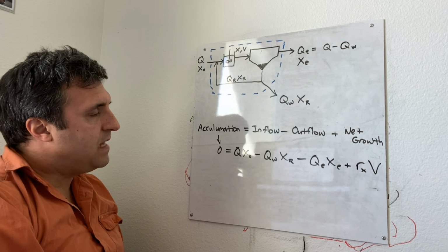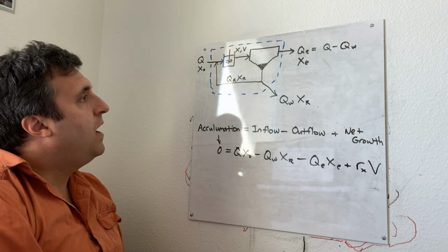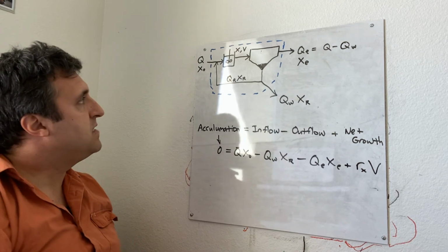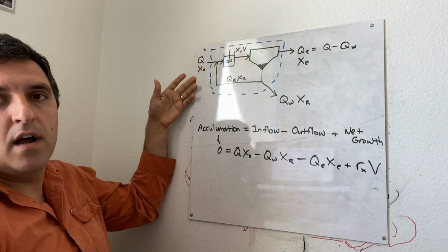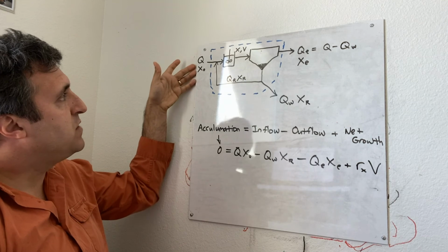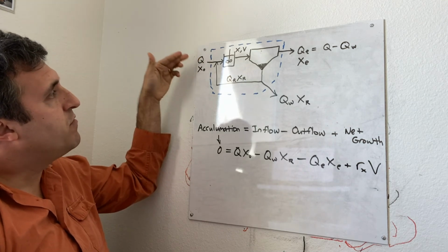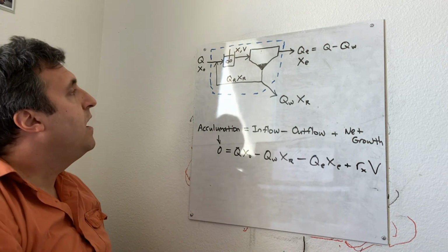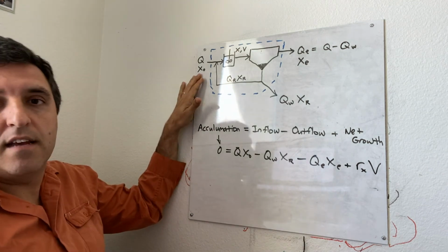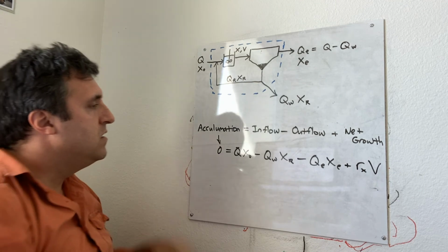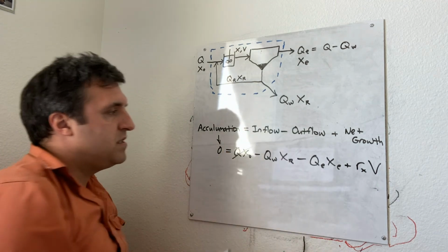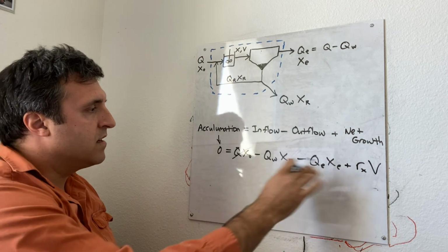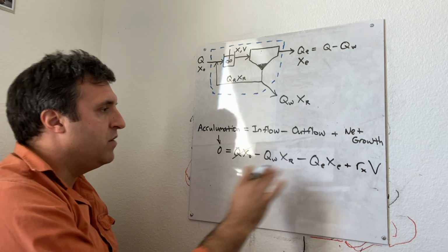All right, so some things that we can assume, since basically what we have is a small concentration of volatile suspended solids in the actual wastewater. There are some microbes in the wastewater that's entering the system, but relative to what grows inside the aeration tank, the concentration of volatile suspended solids in the influent is relatively low. So we can ignore that for the purposes of this mass balance and treat it as negligible relative to the other concentrations and loadings.